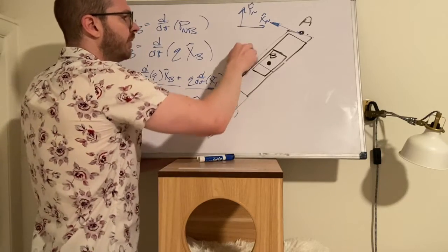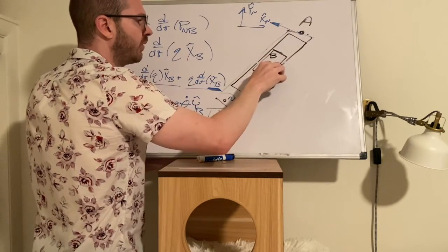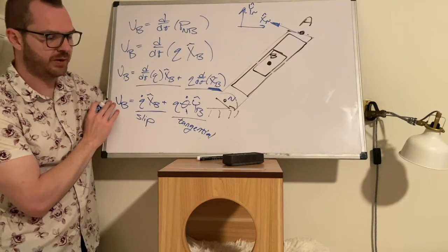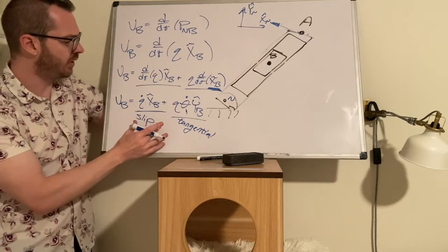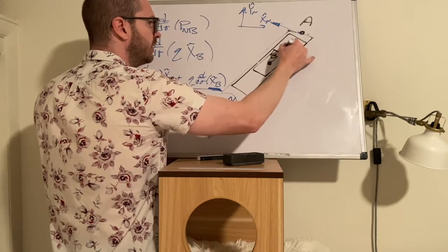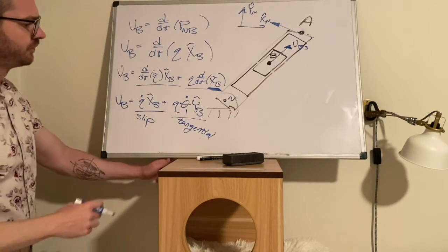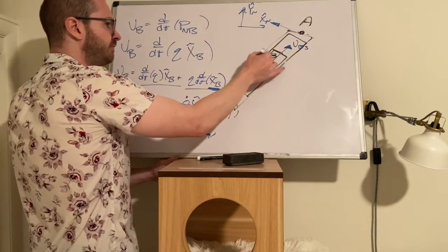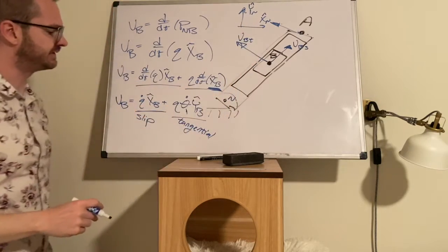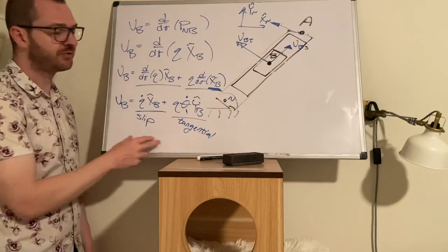If we look at this diagram, we were able to do it for point A, right? We talked about what the velocity of point A looks like. We have an expression now for the velocity of point B. So what does this velocity look like? Well, you have a term in the xb direction. So the velocity of B, for example, it could look like this, and I'm going to say VB S, S for the slip. We have another term. Here is VB T for tangential.